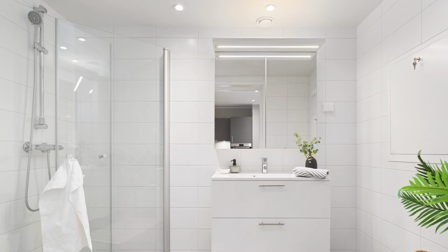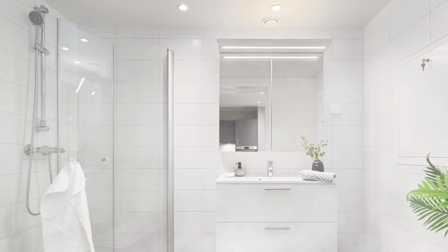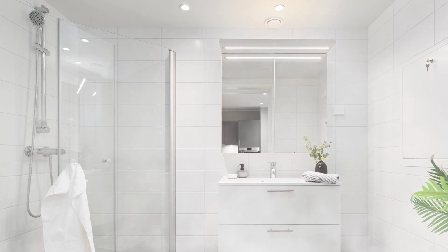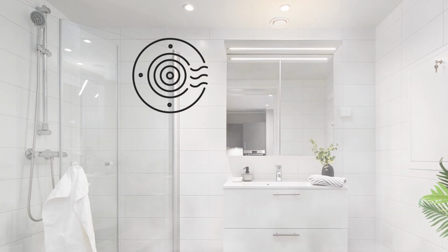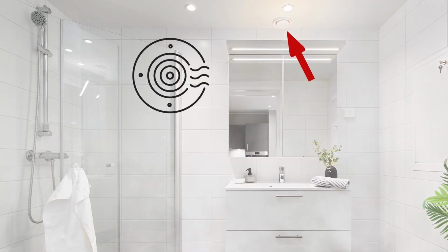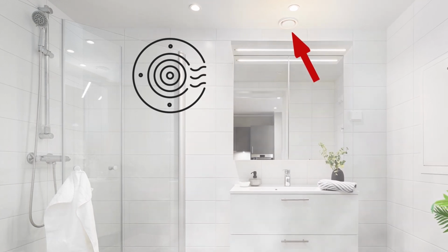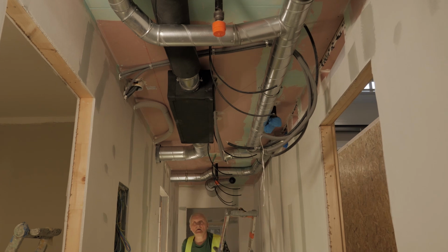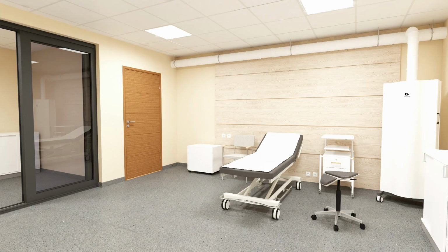During bathroom ventilation, the air enters the bathroom either through a grill in the door or through a gap under the door. Extraction typically occurs through a vent, which is usually located in the ceiling near the shower or bathtub, so that the moisture can exit close to its source. Once the modules are assembled on site, the pipelines are connected, and finishing work is done, only then is the ventilation system finally adjusted for proper airflow.